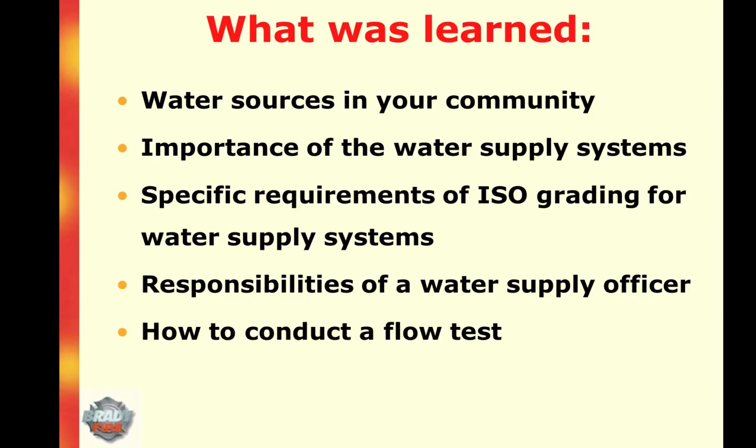Then you flush the hydrant. You take a pitot gauge reading, and then you record the decrease on the residual test hydrant. You draw the curve on hydraulic graph paper, and you use Freeman's formula, which is Q equals 29.83 times the coefficient times the diameter squared times the square root of P.